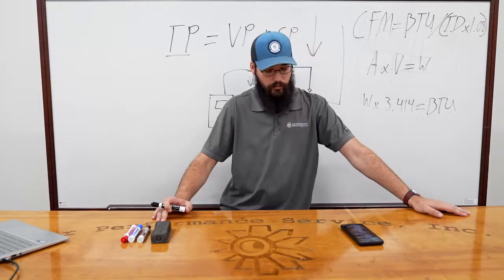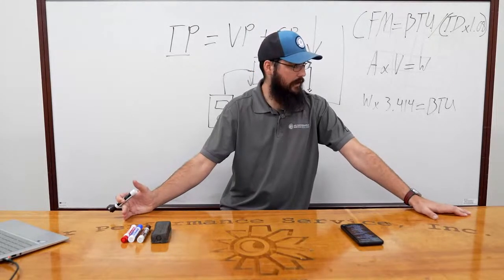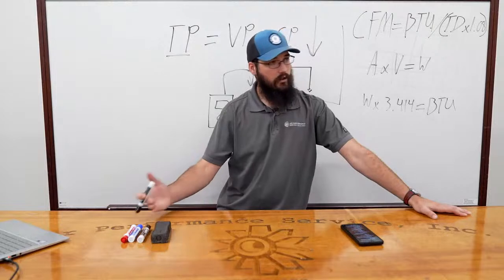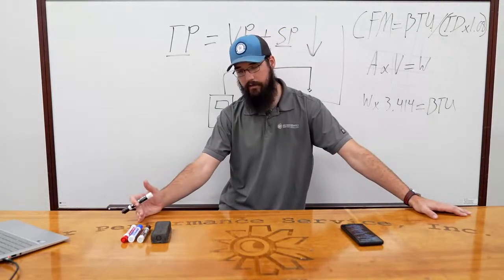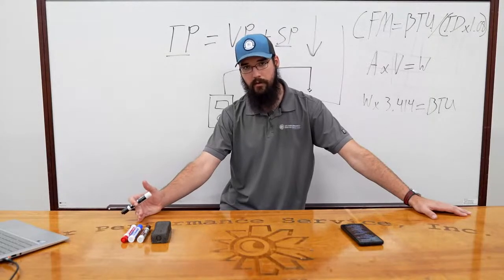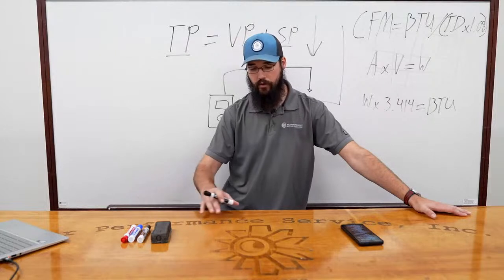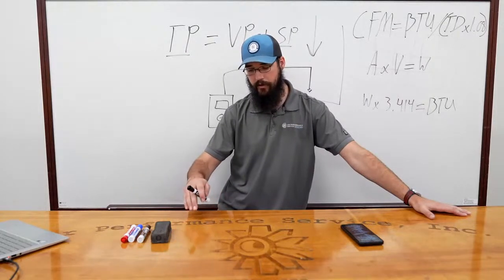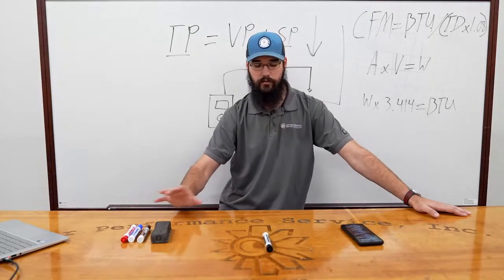Yeah, so density is going to go back to the heat that's in the air. Now, heat includes humidity. So if you're only looking at a temperature reading for the dry bulb, then you're only looking at a part of the equation. And something I want you to understand, this is psychrometrics.